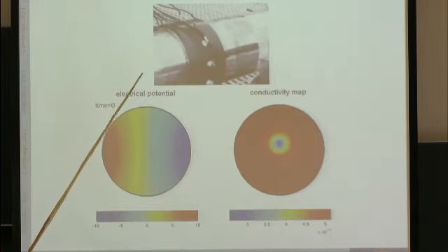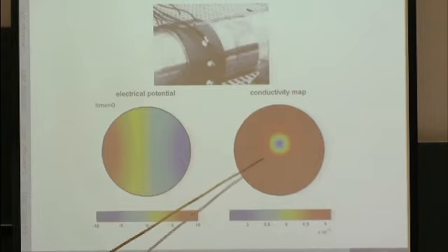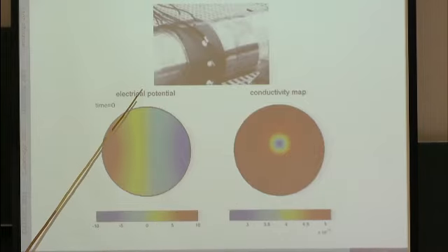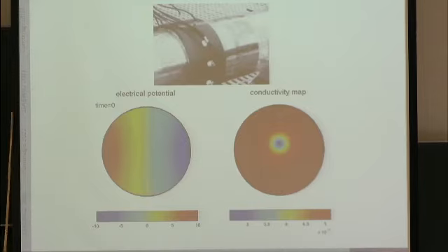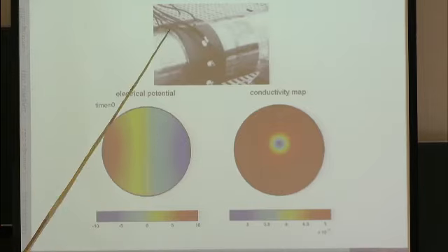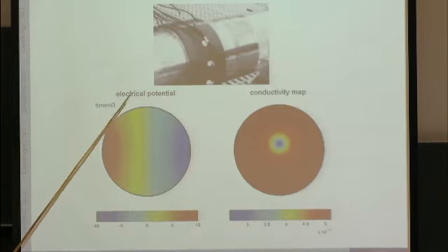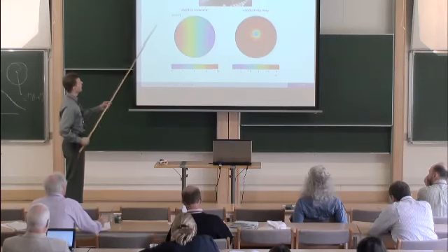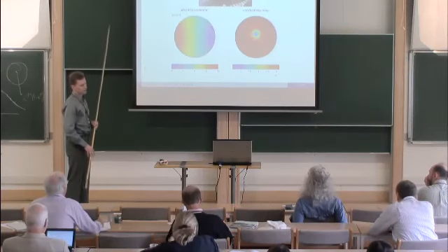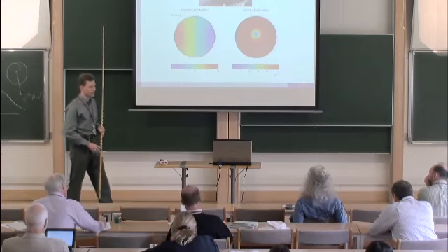Inside the pipeline, you have the oil and gas. So the question is how to reconstruct the interior of the pipeline based on the measurements taken with the measurement electrodes located at the boundary. Some of those electrodes are supply electrodes, so the electrical potential is supplied to the boundary, and others are just for measurement and gathering the data.